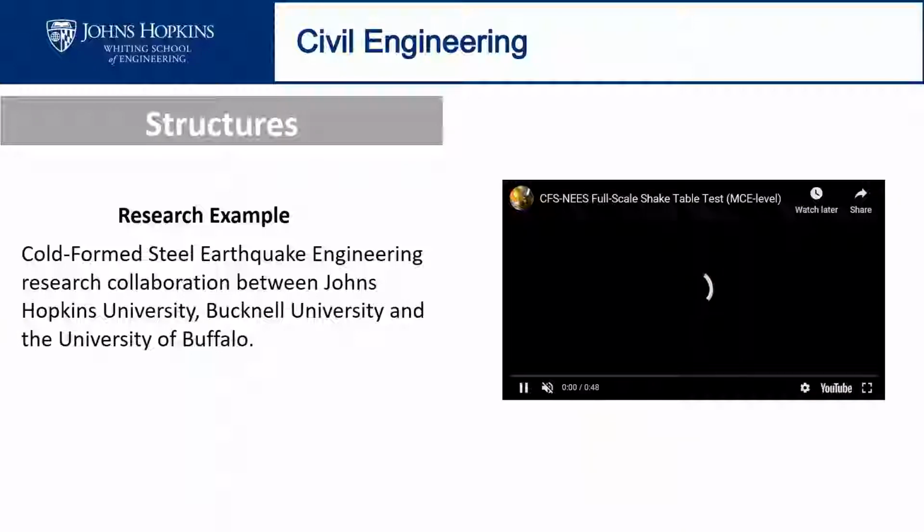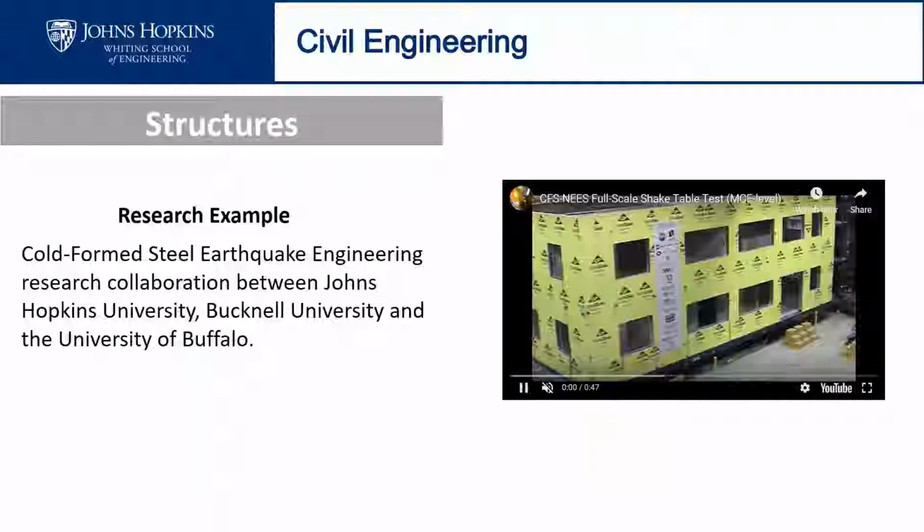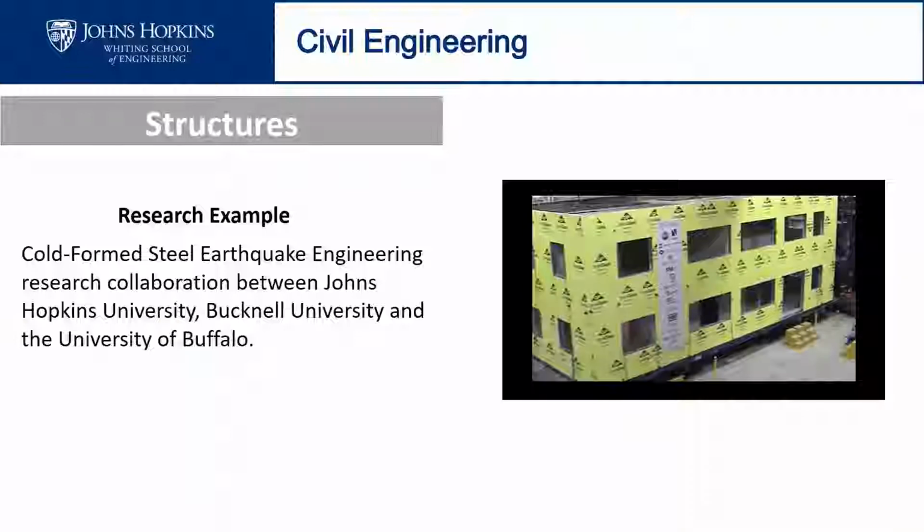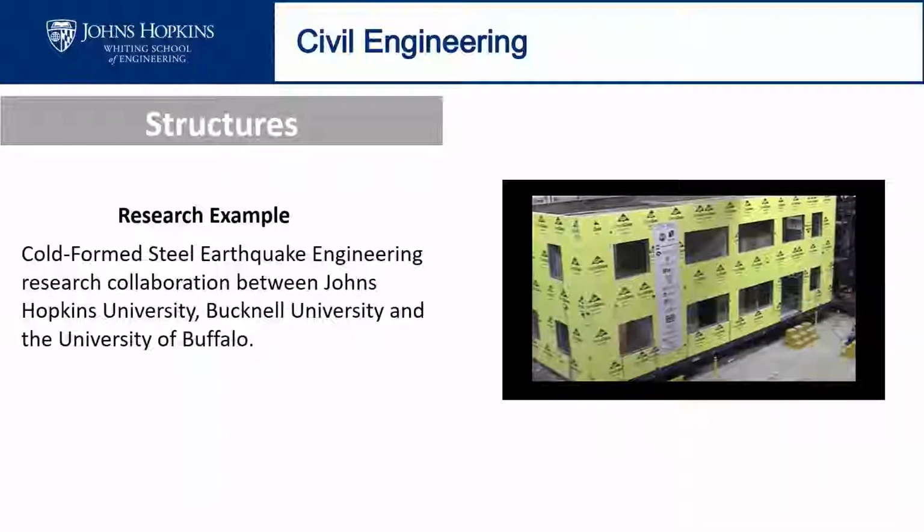So we found that the stiffness and the capacity of the whole building is about 4 to 5 times the capacity that we calculate from the members. So when we only look at the structural members, there's much less stiffness of the whole building. But when we add the drywalls to the building and the outer claddings and the windows, all of that adds stiffness to the whole building. And in this slide, we see an earthquake simulation of this whole building at the maximum design earthquake.